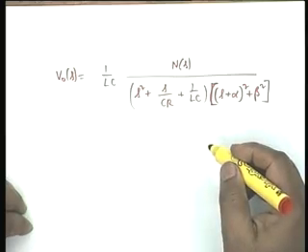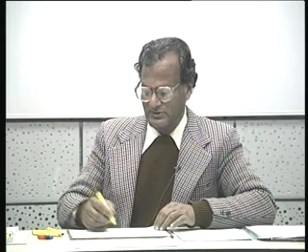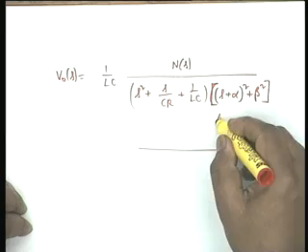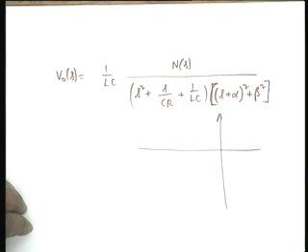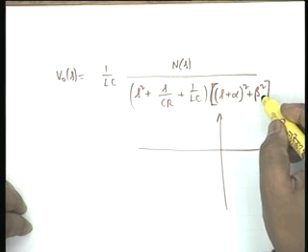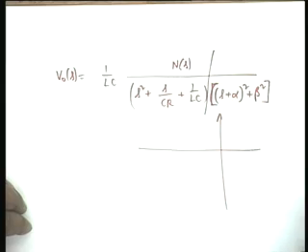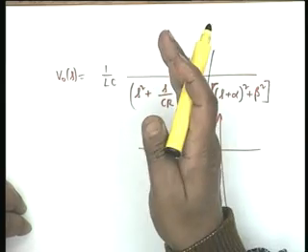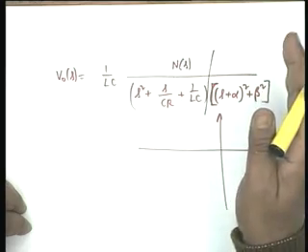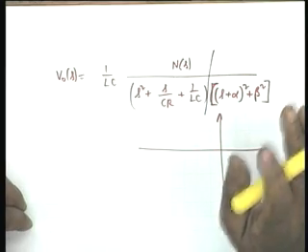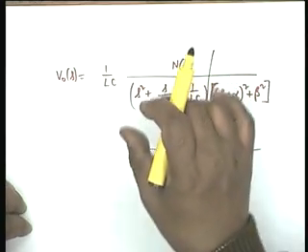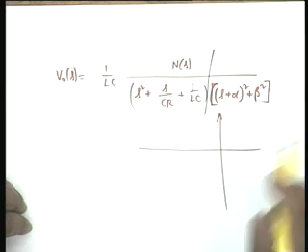Let us say they are complex. A perfectly possible location. Which are the poles of excitation? These are minus alpha plus minus j beta. These come from the excitation function. One part comes from H of S, the other part comes from E of S, that is, network function multiplied by excitation transform.